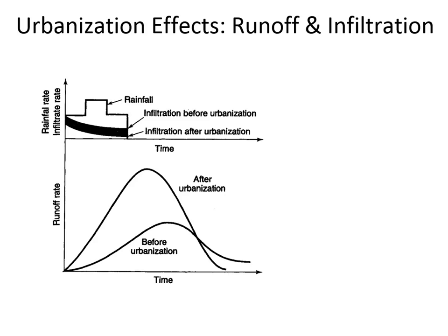Now, during a storm, it doesn't actually rain at some constant intensity and then instantly jump up to a higher intensity. Why do you think that this rainfall chart looks a little bit blocky? Okay, it could be an average, yeah. It has to do with the sampling frequency of the instrument. It may be that the instrument is checking the intensity every 15 minutes, and so it's going to assume that you have the same intensity during that 15-minute period, or in other words, an average over a time. And so that's why it looks blocky.